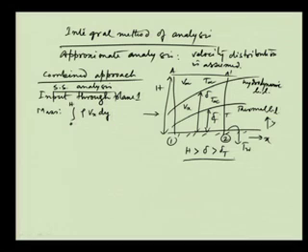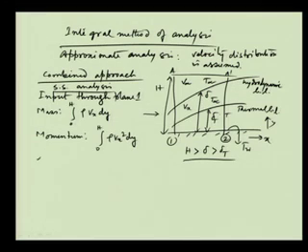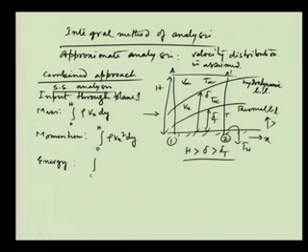Now, the mass is this. The momentum input will be the integral from 0 to h of mass into the velocity, so rho V x square into dy, no problem on that. Then there will also be some energy coming in with this, which is m Cp delta t, and the reference temperature will be taken as 0. So we write the integral from 0 to h of rho into Cp into Vx into t into dy. This becomes the inputs through plane 1.